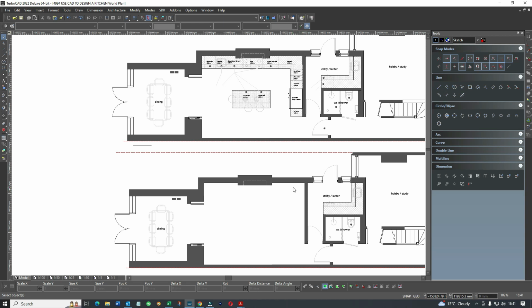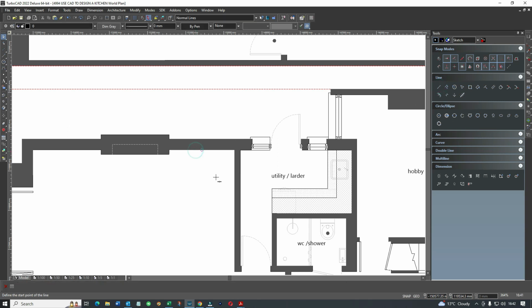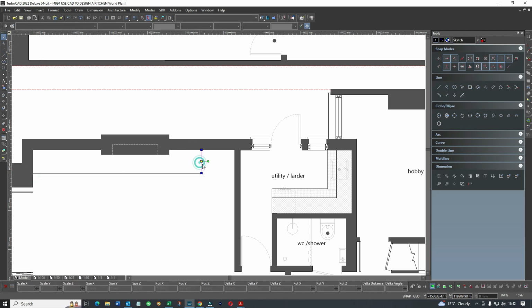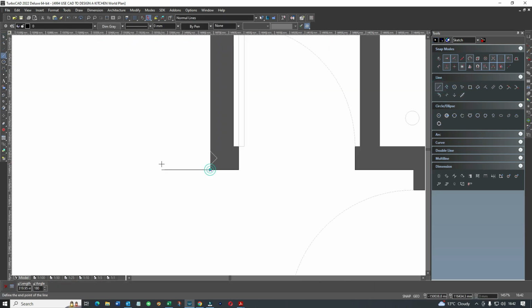Right, now, all good kitchens basically start from a corner. You don't start on an end, you start on the corner. And if we start by looking at the depth of the normal kitchen carcass, we're going to put it at 600. In fact, some of them will be maybe 580, 570, but we don't want to do that. So we're going to go with tab 600 and run a line down, because we're going to do a run of units for both of these walls. So let's get another line down there.